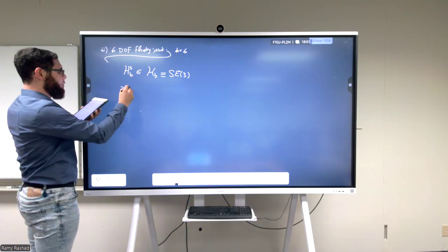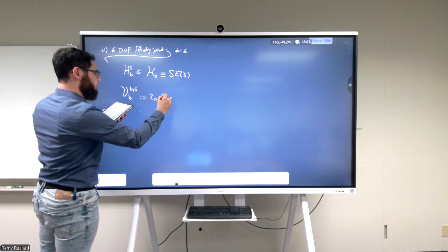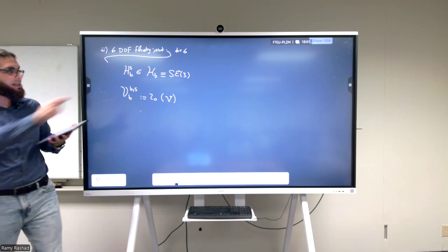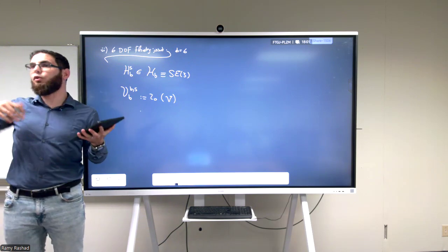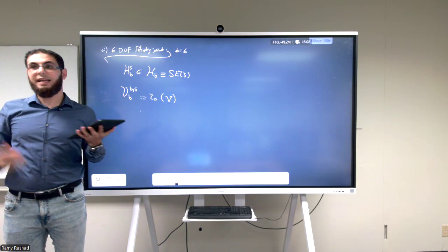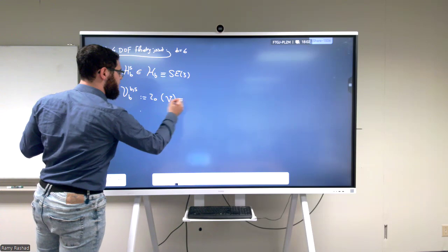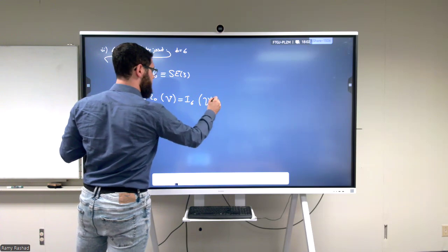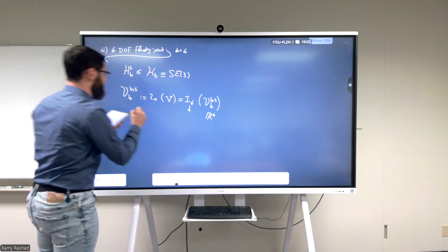What about the twist? V_B with respect to S is given as the definition of something that maps some velocity that describes a generalized velocity of this joint. What is the V here? When we're talking about something that moves everywhere, can we talk about 1 theta dot, 2 theta dot, 3? No, it's a twist. This is nothing else than our identity matrix multiplied by this guy. And you see that this is a map from R6 to R6.